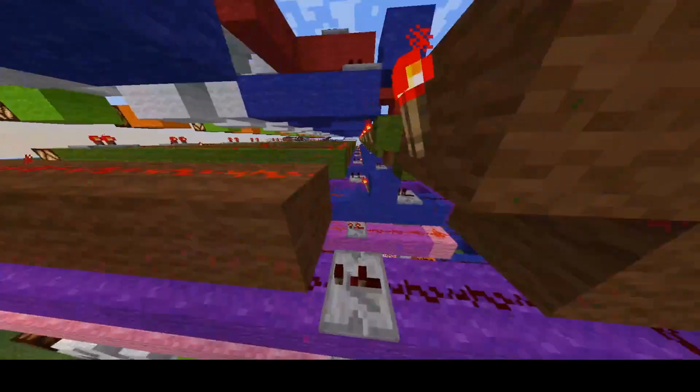It carries from a bunch of AND and XOR gates to another set of AND and XOR gates, and it allows us to add a certain number of bits, as many adders as we make. We could make 8 adders or 7 adders. I'm going to use 7, I think, because then we will have an extra carry out bit, and it just makes things simple.